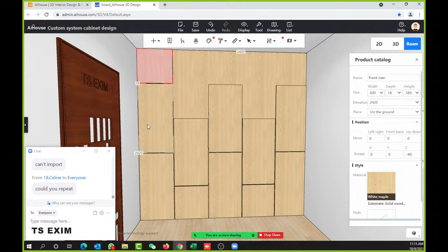Okay, time's up. So this one also same. We will always check the height first, but I did the calculation already. So usually we're less than 1,200. So this is the distance. Then maybe I minus 10 mm gap, should be 1180, the new banner. So I select this one, Control V. Then make it 1180 the height.